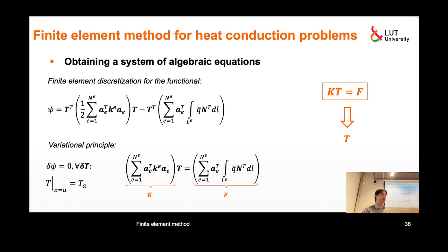What's in the right hand side, we also can calculate if we know the applied heat flux. If nothing is applied, we just assume that it's 0 here. And shape functions we know, and again those matrices describe a connection between elements. So once we know the mesh and we know everything about the finite element, how it works, then we can solve this problem and find those values of nodal temperature. And that concludes the theoretical part of finite element methods.